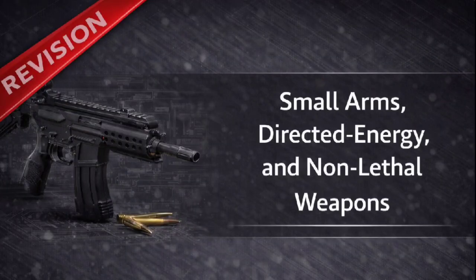So gas operation wins on adaptability, but what does recoil offer that gas can't, especially for specialized vehicles? Recoil-operated systems are exceptionally sturdy, and critically, they are the standard for weapons used inside armored fighting vehicles, or AFVs. Because of the fumes. A recoil system maintains a fully locked breech until the internal pressure drops to ambient limits. This means no toxic propellant fumes are immediately vented into the crew compartment. Whereas a gas system vents right away. It vents fumes immediately through the mechanism. It's completely unsuitable for AFV use. Plus, gas systems typically have a much more complex procedure for changing barrels, as the whole gas block assembly has to be mated correctly.